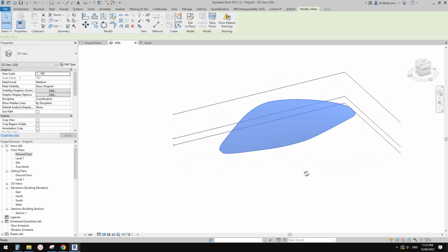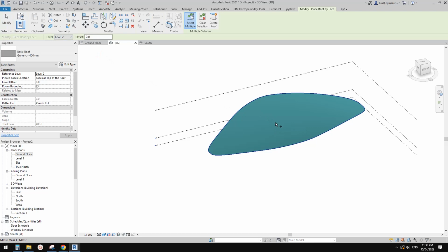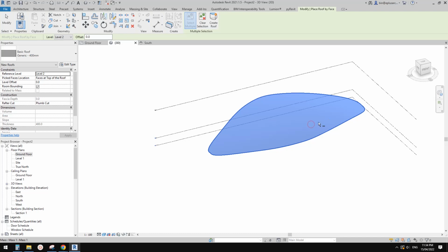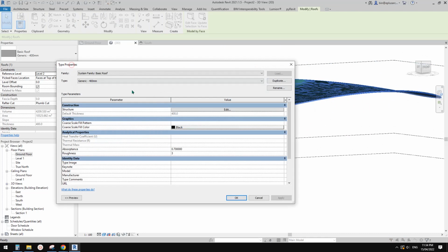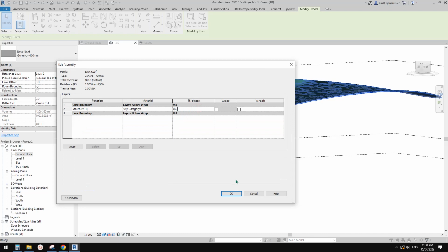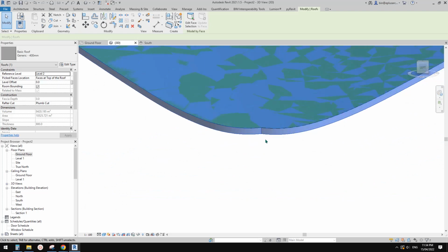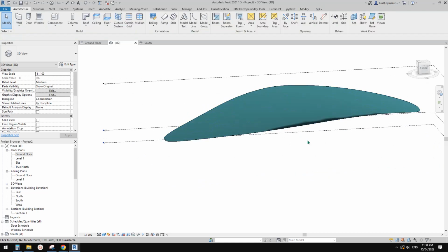So this is the shape of the roof, and then you can place a roof by face onto it, so you can have some thickness. Oh, hang on. Did I just click the mask first and then create a roof. So this will create a roof with thickness. So you can adjust thickness to whatever you like. So because this is a big roof, so just make it thicker. Yeah, just ignore that. Okay, so let's just delete this roof.